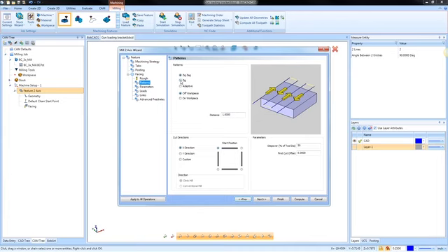So we have zigzag, which is bidirectional, zig, which is single direction, and then we also have an adaptive, which is similar to a spiral where it will work its way in. Mill multi-axis is that 5-axis stuff. It's not accessible on my standard V31. Yes, John, mill multi-axis, you'll gain access to that as a mill premium. Excuse me, a mill premium user or a 4 Pro, 5 standard, or 5 Pro will get access to those toolpaths.